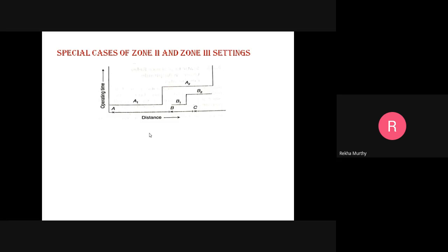So in this diagram, this is what the second zone adjustment has been done with the additional time for the selectivity with a relay of very short adjoining line, which you can see here. Earlier we had considered 80 to 90% of this, so now it has been increased further, and this was around 50%. Again, you can see there is a small change.